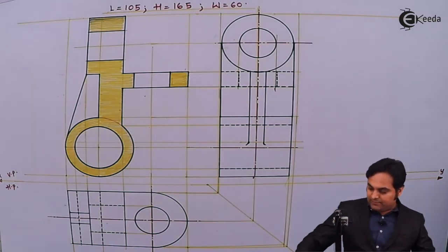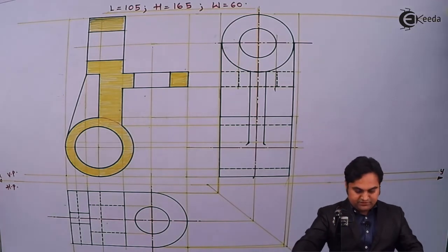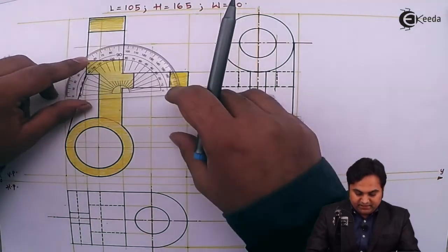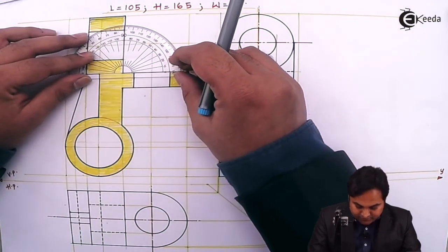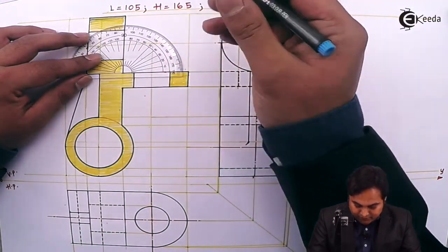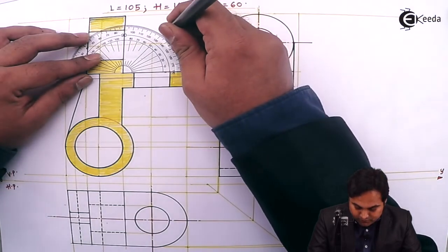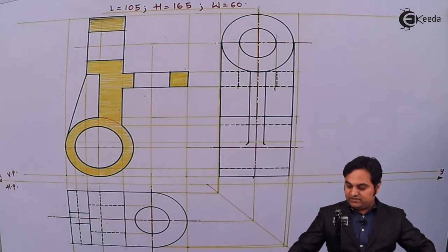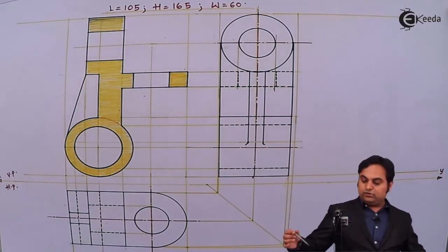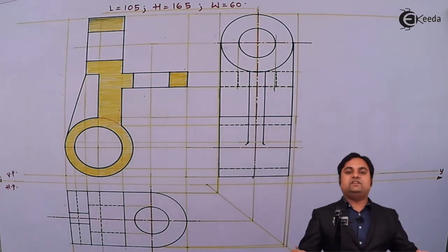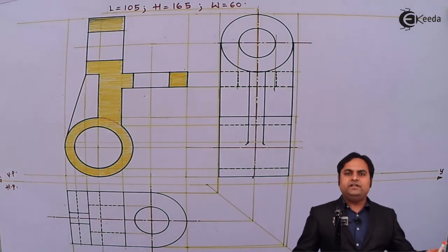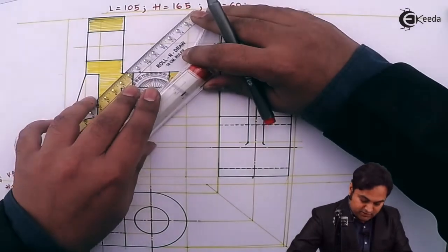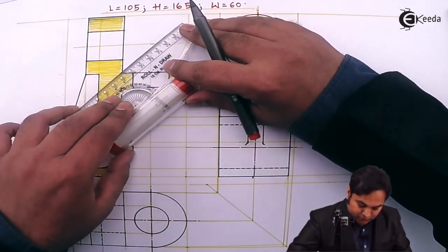For that I am selecting a point as the reference. I can take any given point in the diagram, like for example here, and I'll mark 45° with respect to this point, and then taking this as the reference, here I'll draw the section lines, and for the section lines again they are also medium dark lines, so I'm using red color which indicates medium dark as per the convention which I have provided.